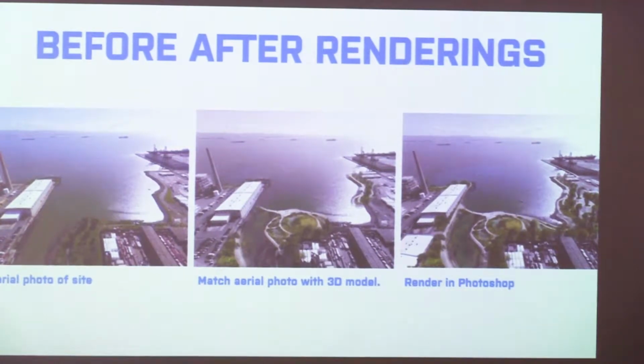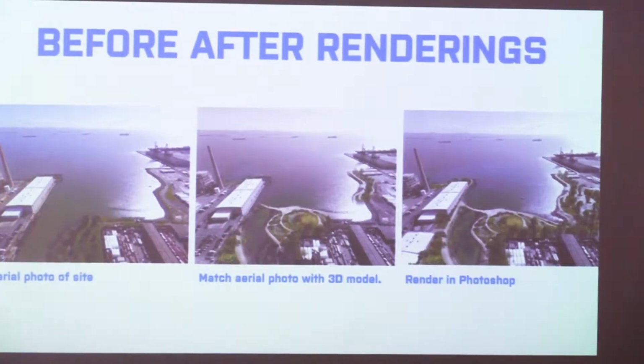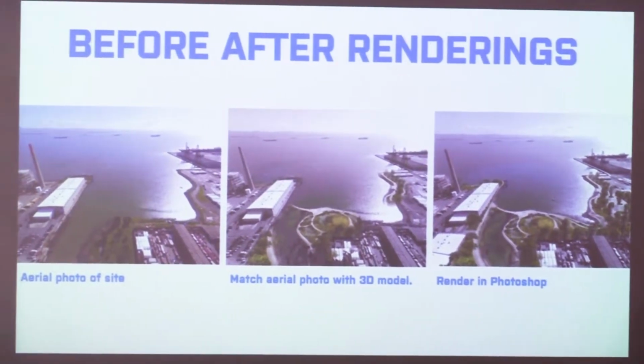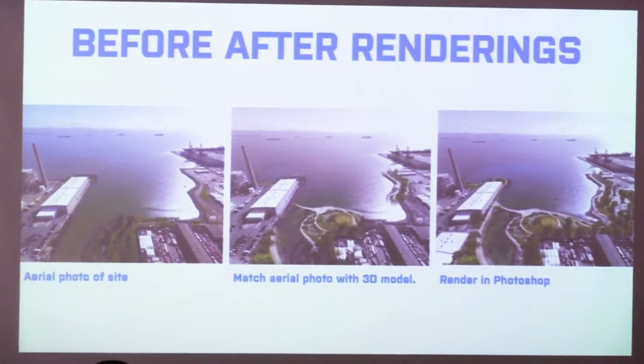Another way to use aerial photography is for before and after renderings. In this example, I took a photo from a project site and I noted down at what elevation I was taking the photo, which angle the photo was pointed, and the full field of view of the camera. And I was able to match that view exactly in SketchUp and then overlay that rendering in Photoshop to create a perfect before and after rendering, which is a great tool because you get all the accurate context and it really helps the person who's viewing it understand what the design is.